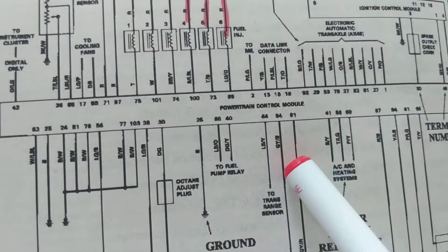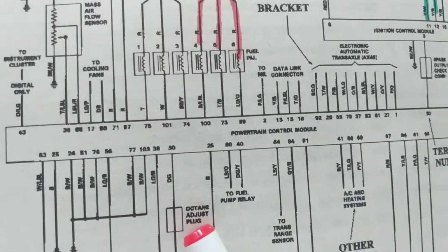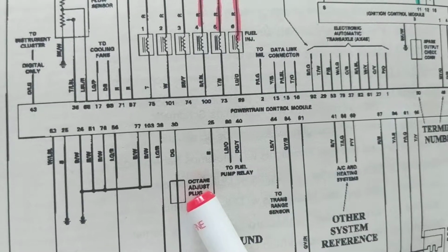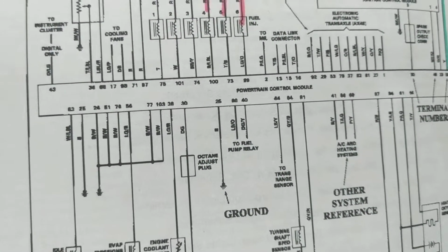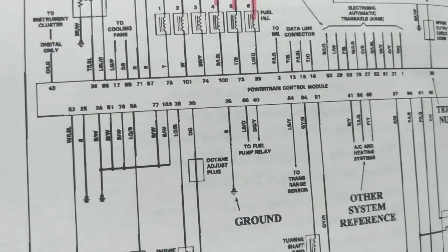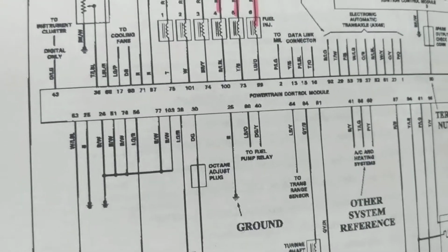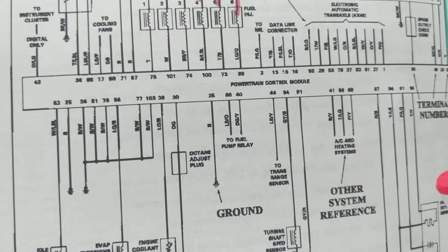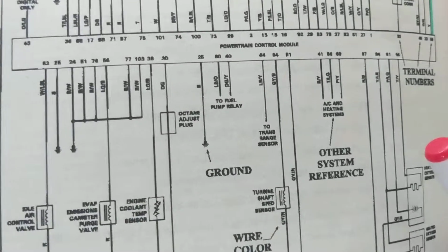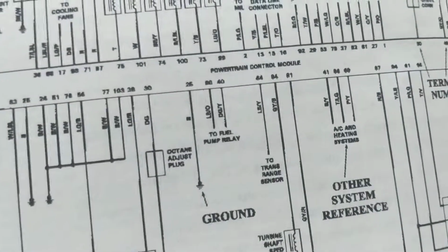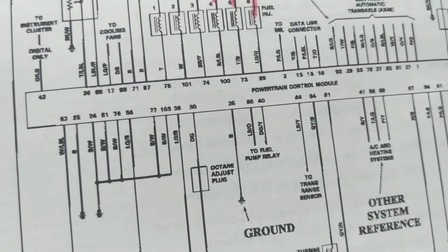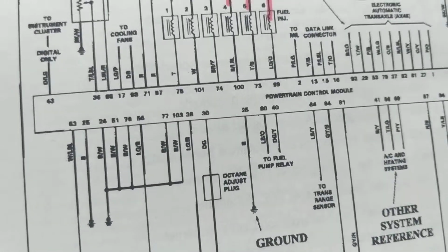In order to control how much fuel goes into each cylinder, we have to know the air mass in grams per second. Mass airflow sensor tells us this. When we open throttle, which means we're accelerating on the gas pedal, we're opening up something called the throttle body.